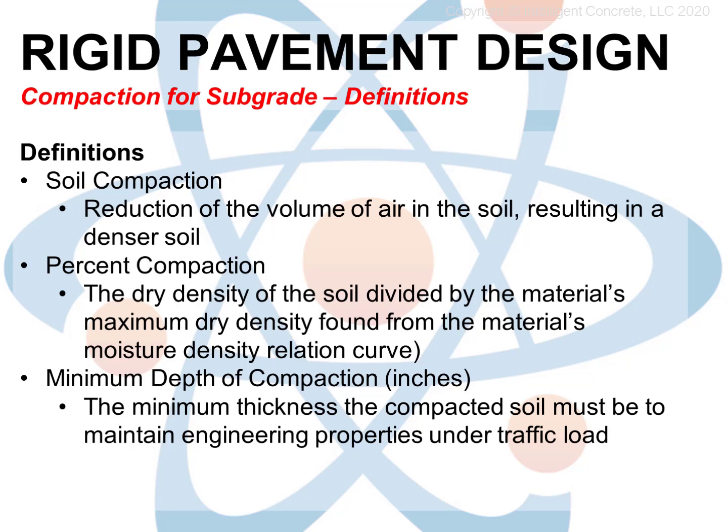Roadways and pavements usually use a modified Proctor density, which provides a higher degree of compaction, and again, normally 95% is the minimum specification. Don't worry, neither of these will be on the test. A minimum depth of compaction is a function of how deep we must go into the subgrade, that is, the native undisturbed soil, with constructed layers of densely compacted structural layers of soil built on top in order to achieve a stable surface upon which we can build our pavement.